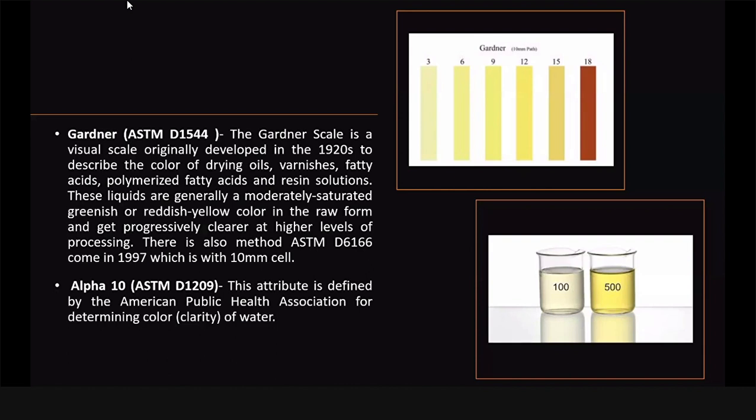If it is a sea discharge, mostly they apply Gardner, because Gardner has a scale from clear water to dark reddish, dark yellow and reddish greenish tone, which is maybe the highest. APHA has a little lower scale, so we call it in-house discharge, and the other we call public discharge.